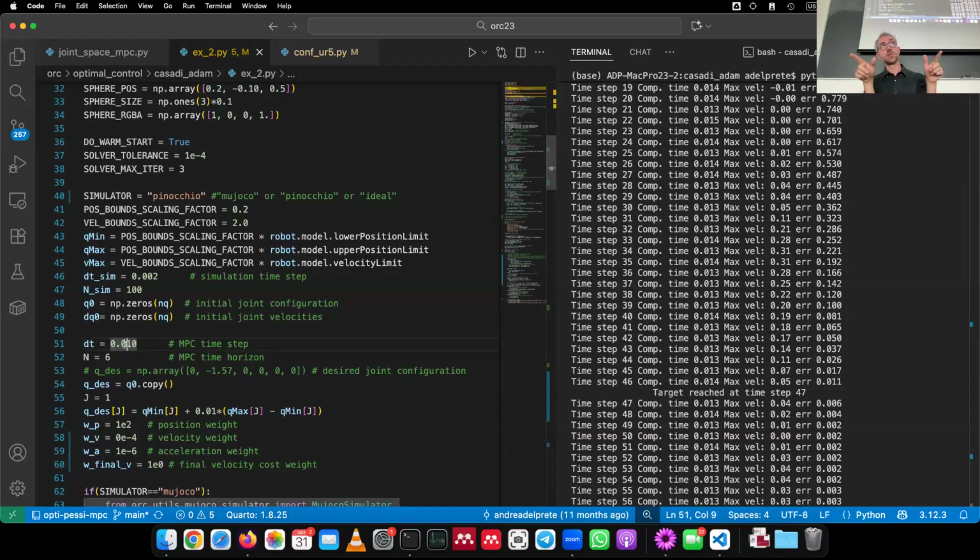I didn't get how the input would deteriorate if I change the integration scheme. No, changing the integration scheme doesn't affect the other stuff, but the idea is that if you change the integration scheme to a high order scheme, like Runge-Kutta 4, that allows you to use a much larger time step.